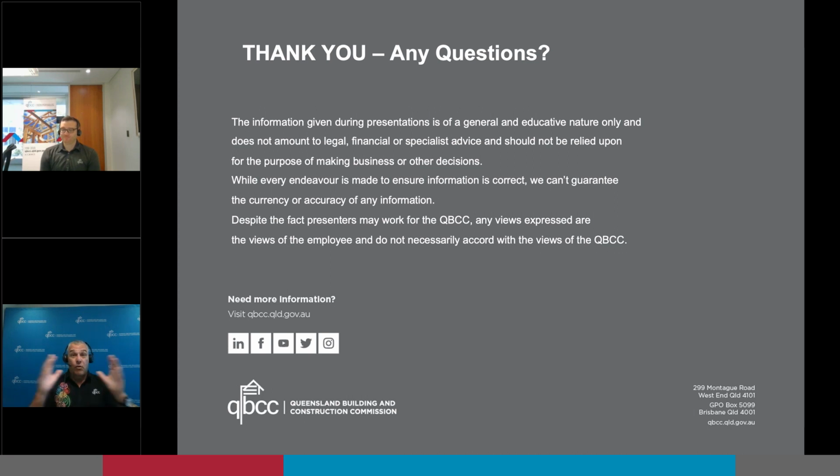So yes, it is a very broad definition, but it's important to ensure that the product is something that is or could be associated with a building. Remember, under the legislation, associated with means incorporated into or connected to a building by carrying out relevant work, which is defined under Section 5 of the Building Act for those of you who are looking. And so to answer your question, paint would be considered a building product as it's applied to or incorporated into the building. Thus, it's a thing that is associated with the building, so yes, it'd be a building product.